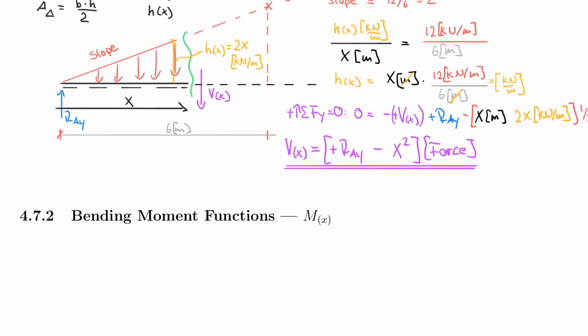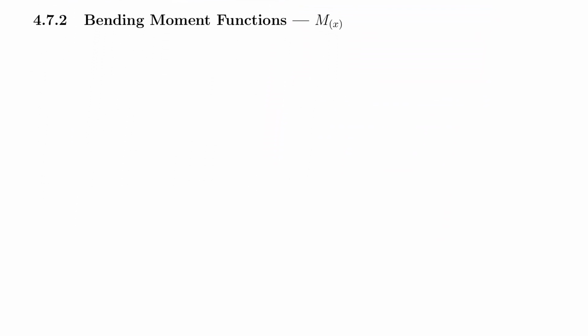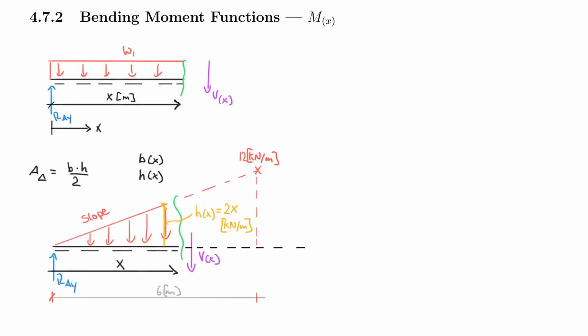All right, so for the bending moment, we will do the very same thing. In fact, I just copied the entire pictures from above and brought them in here. Now to make our life easier, I will erase these shear forces and replace them with the internal moment, because now we worry about the moment. So I have this as a moment and this as a moment, and our goal is to express M of x and M of x.